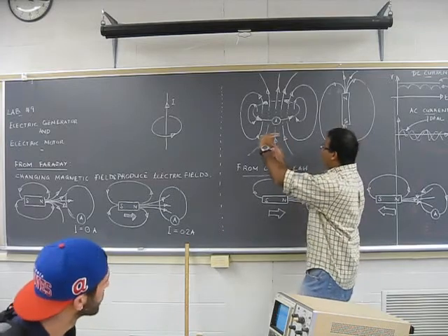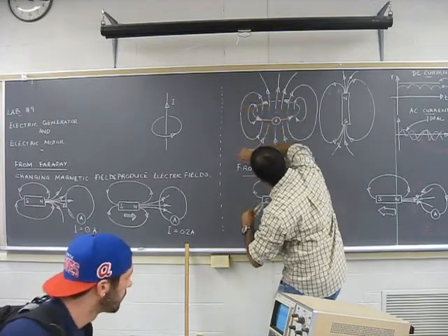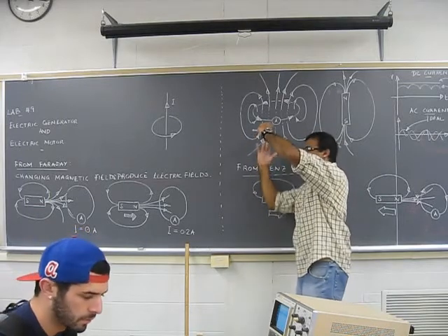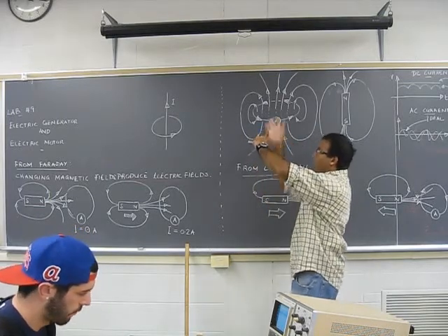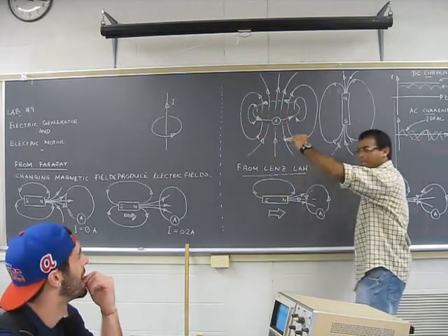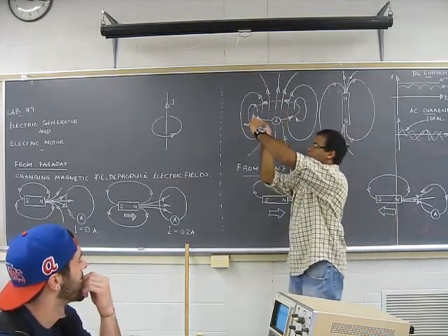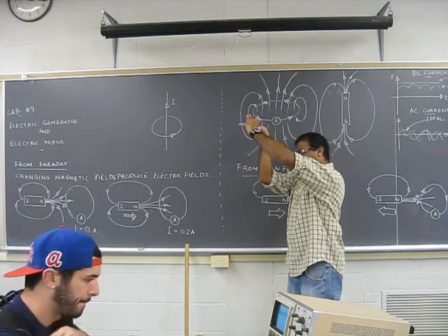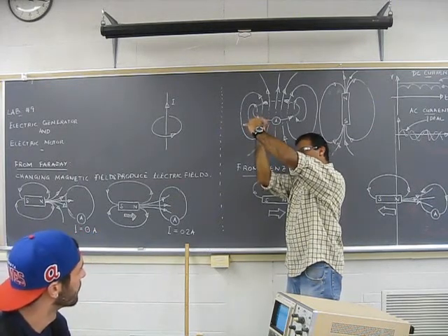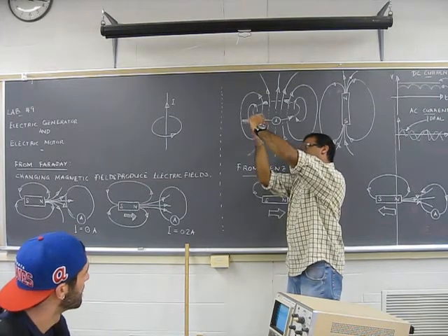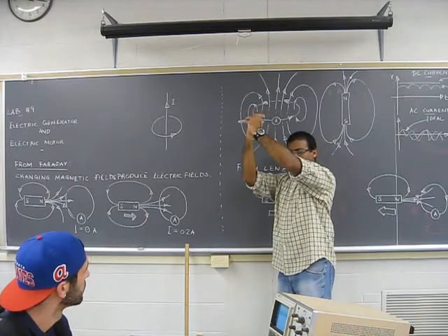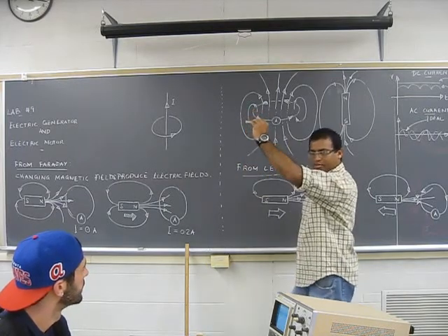And if you look at the bottom, you need to make sure that the field lines are continuous. So at the bottom, they come into this loop. On the top, they move away from this loop. Okay? So how do I know this? Put your right hand, thumb to the direction of the current, and then the rest of the fingers you just try to grab the conductive wire. So when I try to grab this, this is the direction I get from my fingers, and that is the direction of the magnetic field.